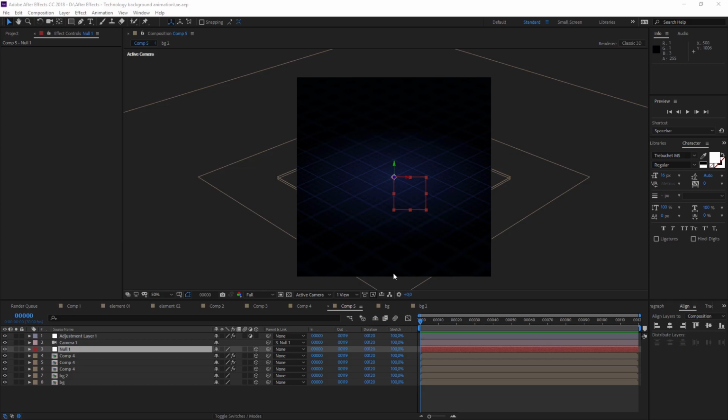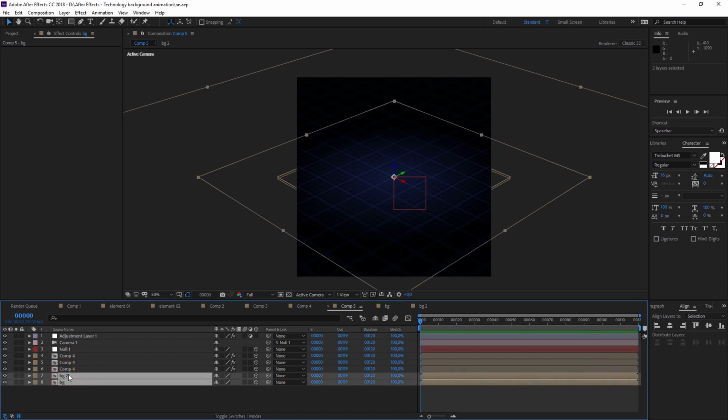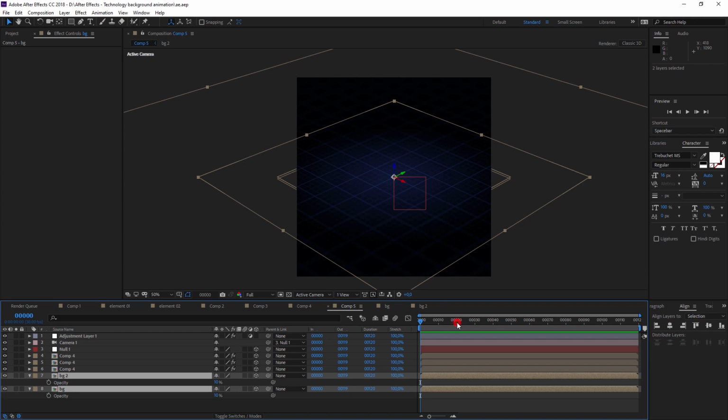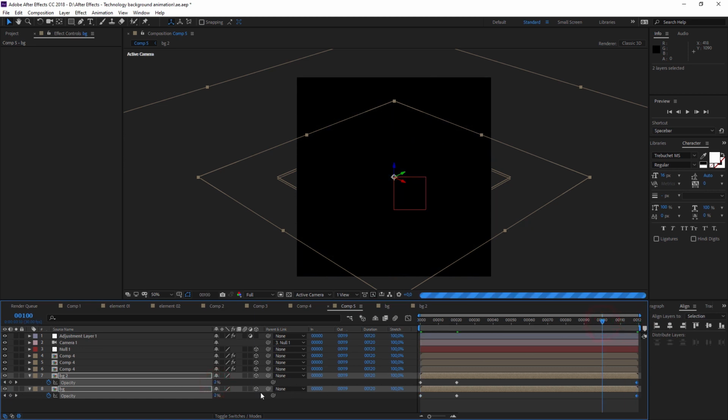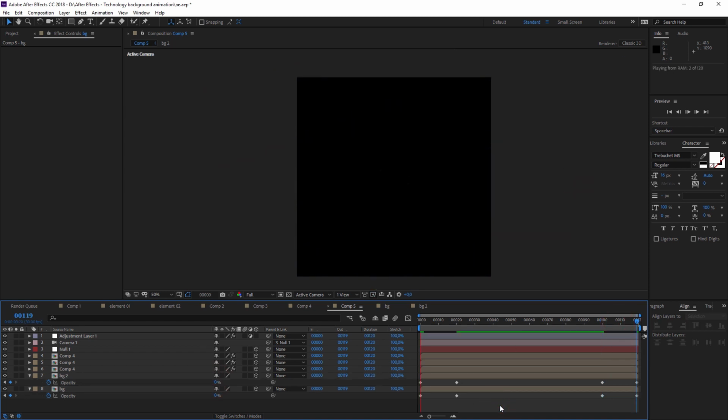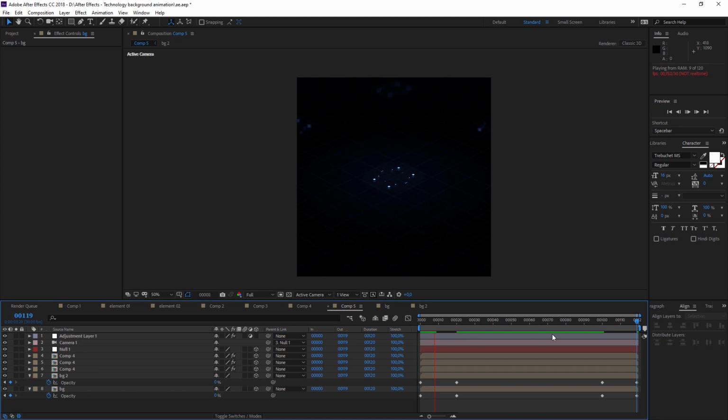As I said in the previous lesson, before we finish this class, I'll show you how to improve this thing. First of all, we have a few frames at the end and the same frames at the start. So I would like to suggest creating some fade-in animation. So 0 and fade out, 10 and this fading. And it brings more life to your scene. It's more logical, so we have some flashing in, then we have our detailed animation, and then we have fade out. So let's calculate this thing.